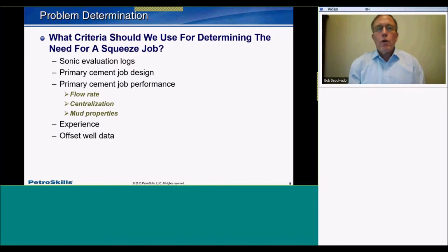Also, the differential pressure. We've already ascertained that we can calculate volume of cement on a casing job. Well, there's a differential pressure as we displace the fluid, and that differential pressure should be based on the height of determined cement in the annular area. Was that close? Was it far off? Why was it far off?